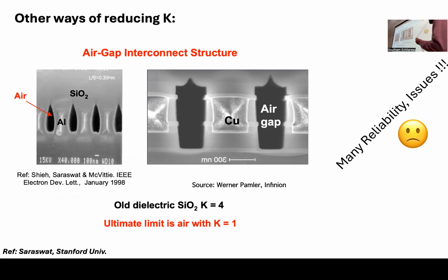There are other ways to lower the dielectric constant. Rather than having the dielectric uniformly distributed, even in your transistor, you can keep some open spaces, like here there's air, and then overall the effective dielectric constant is now lower, right? But typically this is not used because it has many reliability issues, obviously mechanical issues, and so on. So typically people don't leave these kind of empty spaces in the cross section. Also, when you do processes like annealing, these air pockets can expand and cause breakage, right?